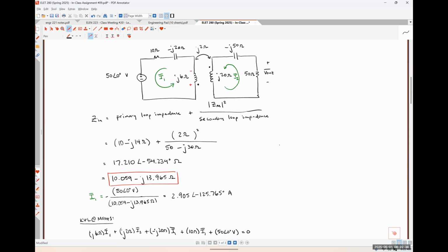Brandon. Why wouldn't the J2 be negative? Okay, so fantastic question. So when we are determining the sign on the mutual inductance portion of our voltage, the first thing that we do is we check to see if the positive polarity terminal of our voltage is at the dot or if it's at the undotted terminal. So in this case, it is at the dot, right?